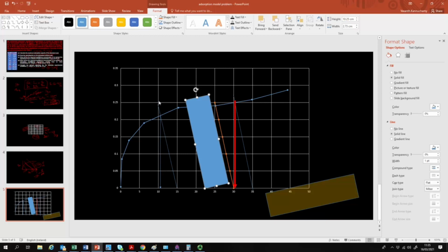Yeah? So try to check it. You have to buy a graph paper, plot these values, and then draw the operating line, and then use the scale to draw some lines parallel to your operating line, and from that you can calculate your CE value.